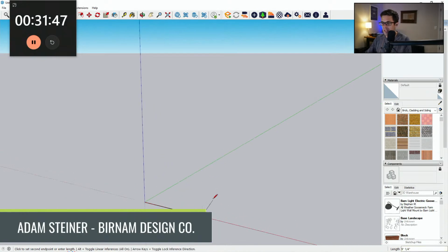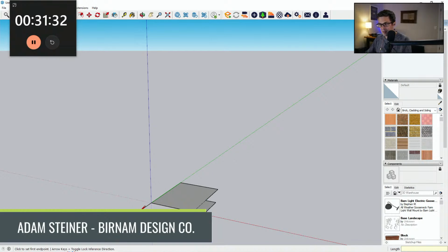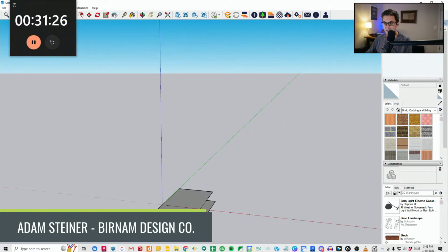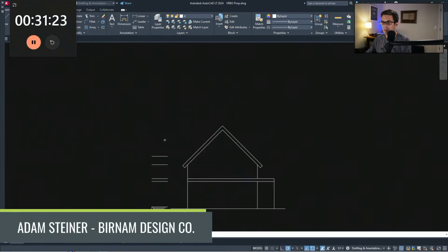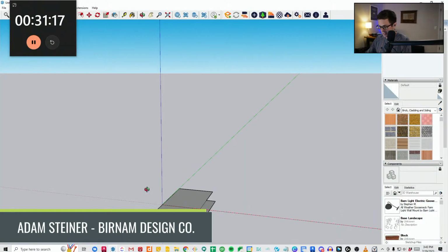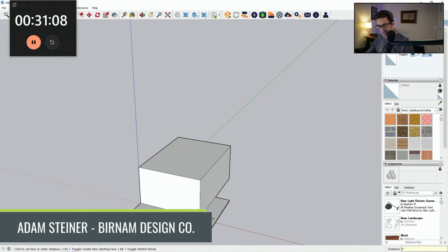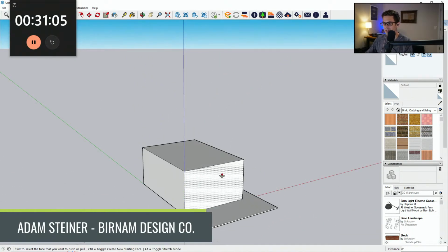Okay, so always with SketchUp, I just start by drawing my footprint. That's 25 by 34. Then I came 12 feet out on this. There's another 6 feet out, and I think 16 back that way. Oops. Those lines have to snap or it will be a mess. Okay, back to CAD. So that shoulder height, 15.9 and an eighth. Let's just do that. 9 point, not 2.5, 1.25. There we go. Okay, this patio coming up 4 inches, slab on grade 4 inches, so it's roughly 4 below